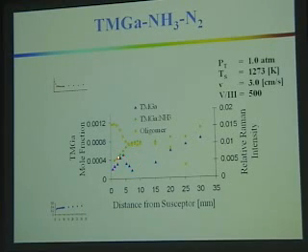The more trimethylgallium starts to appear, it starts to react and we form even more oligomer. And so the key to designing this reactor is to prevent the formation as much as possible of the oligomer and to deliver as much as you can of the trimethylgallium right at the surface so it can be reactive. And this is what that cross-flow design that Nakamura came up with did effectively, and what the new reactor design does effectively as well.